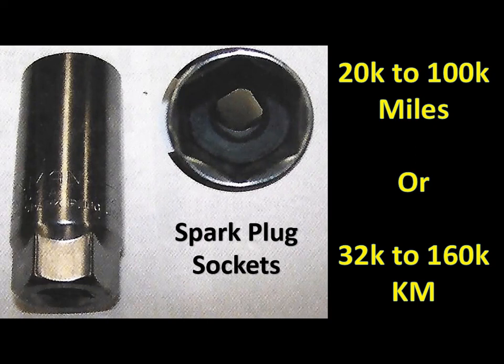As a general rule, all spark plug service is done when the engine is cold. Aluminum engine cylinder heads are particularly susceptible to damage. If the spark plugs are removed when the engine is hot, often the threads are damaged if extreme care is not taken.